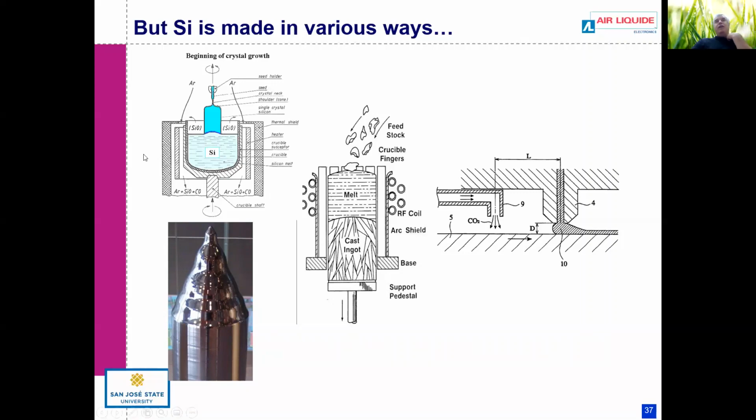And so then you recondense the hyperpure silane, right? And then you have to go through another process to get the hydrogen off of the silane, SiH4, so that you just have Si left over, and then you melt that in one of these crucible furnaces, and then you take a single crystal of silicon, called a seed crystal.